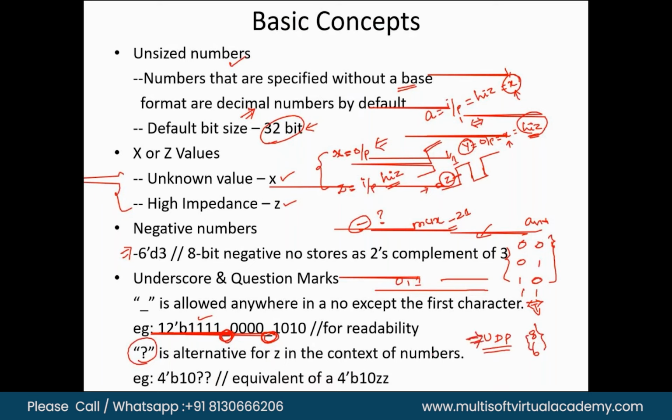In that case, the Z comes into the picture. I can take one of the inputs as Z and the other input as 0. And likewise, both the inputs are 0, Z. Then what will be the output? Like this, I can write code using this UDP.